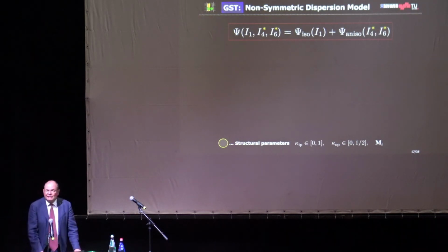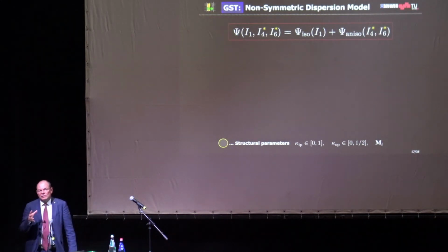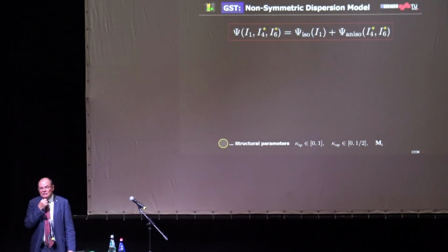Well, in terms of finite element, we have used a mixed formulation because we have the incompressibility here, J equal to 1, so we use an augmented Lagrangian iteration in order to constrain J equal to 1. When you use a normal Galerkin principle, a displacement-based finite element, that will not work because it will lock. So we used a mixed formulation. This is the first answer.